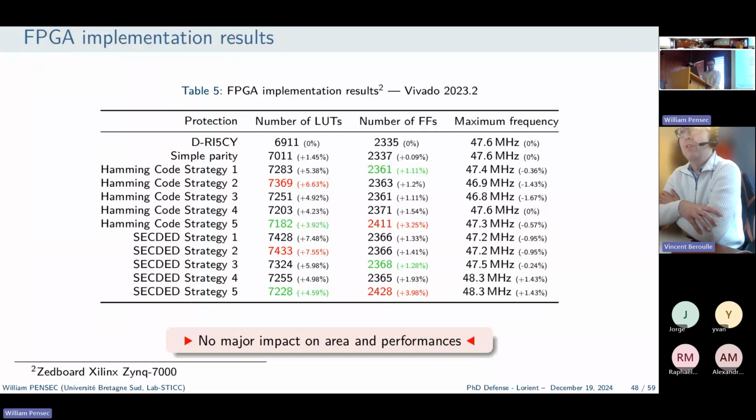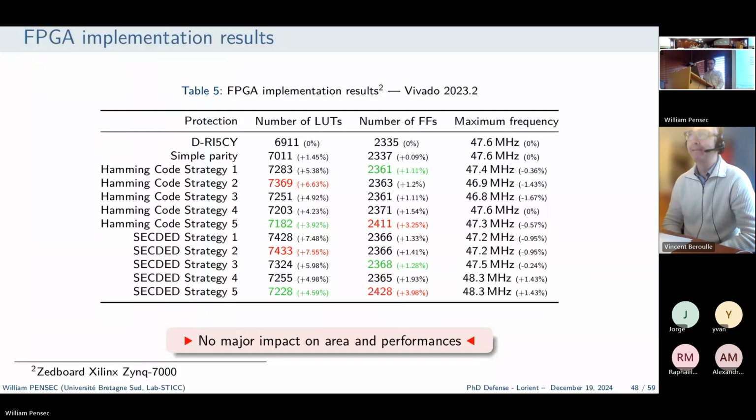And do you think another countermeasure could be to make this synchronization more difficult, to avoid this attack? For example, as a hardware countermeasure, we could use obfuscation. We could imagine adding some random dummy cycles, maybe more before the raise of the propagation of the signal for the exception, so it will be more complex for the attacker to know exactly when to inject the fault. Yes, I agree.